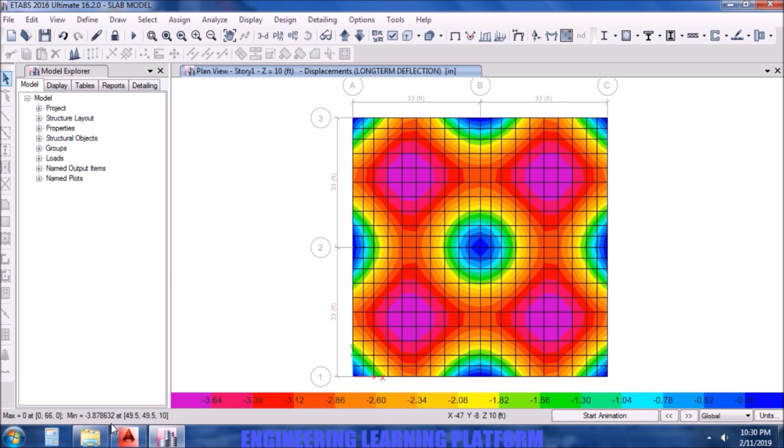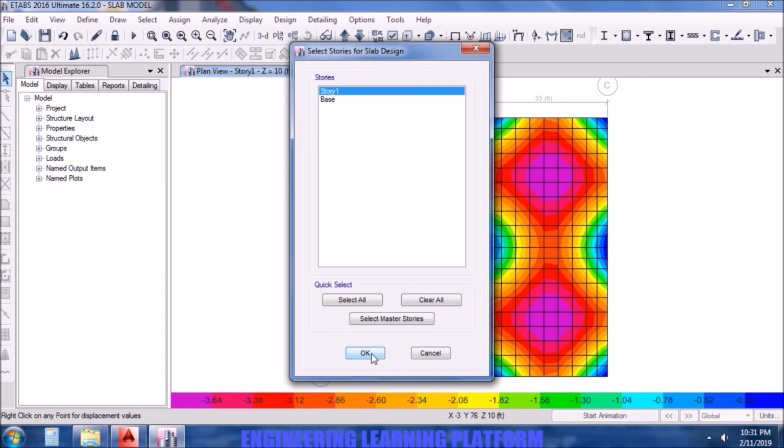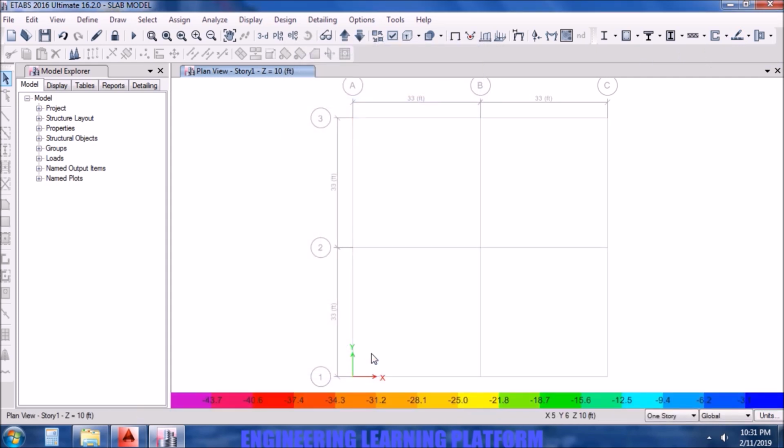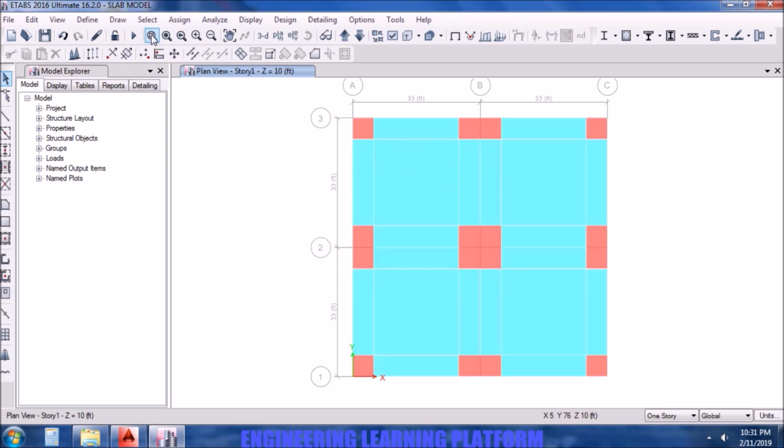Deflection limit is still exceeding after running the model again and again, but we cannot exceed the limit of 17 inches of slab thickness and waffle thickness due to architectural purposes. We are restricted there. So the last option is providing camber.